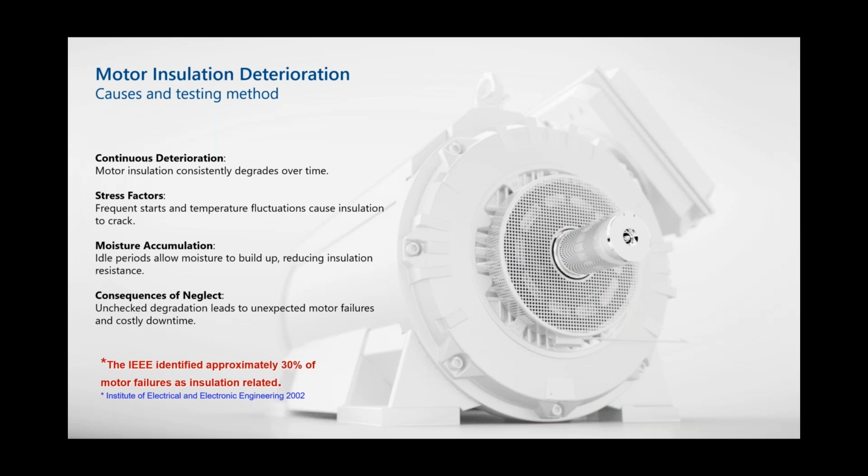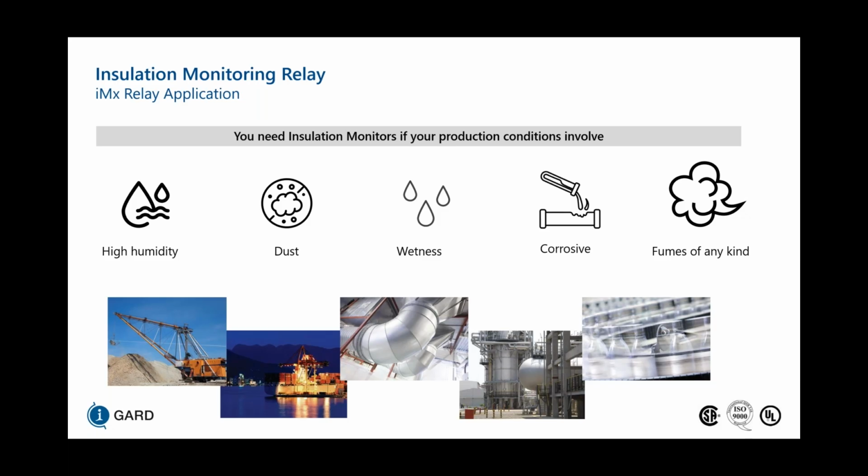IEEE identifies approximately 30% of motor failures as insulation related, and that's coming from IEEE 2002. So you need insulation monitors if your production conditions involve high humidity, dust, wetness, or a corrosive environment where there could even be fumes in the air as well.